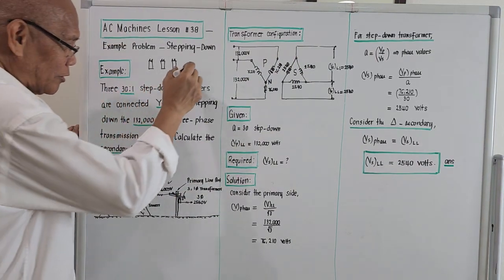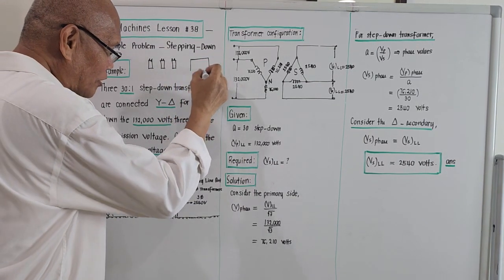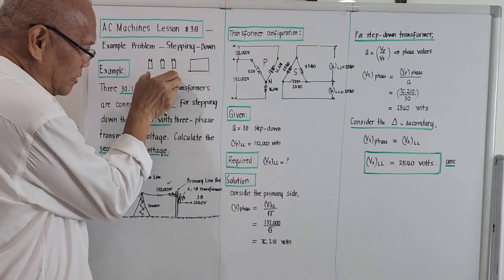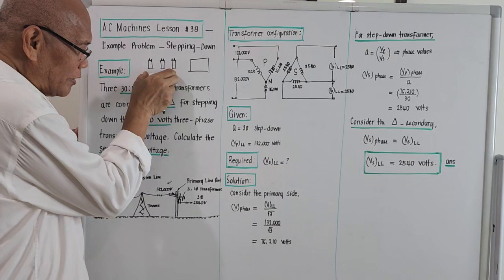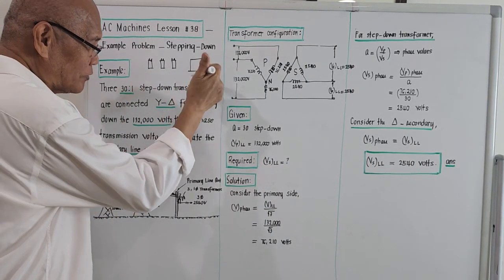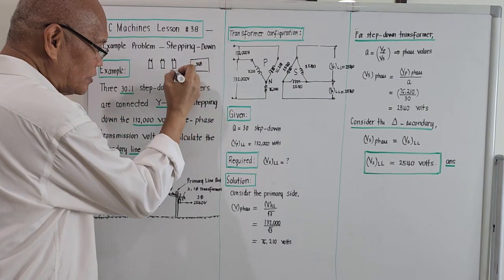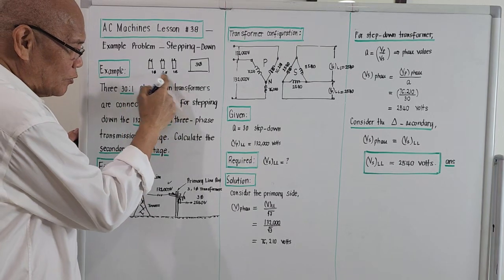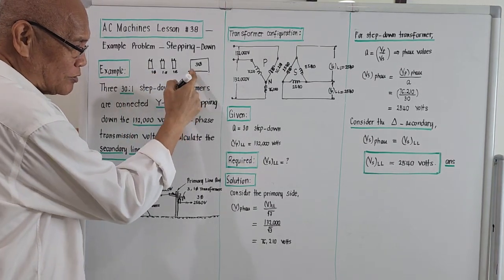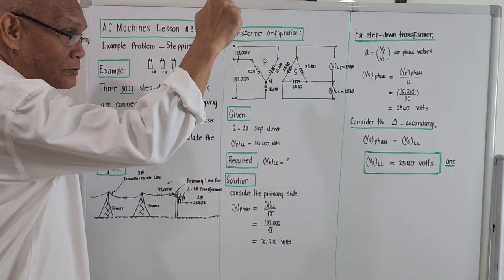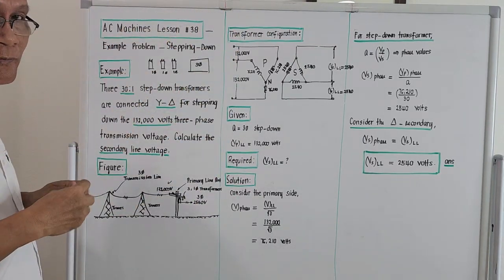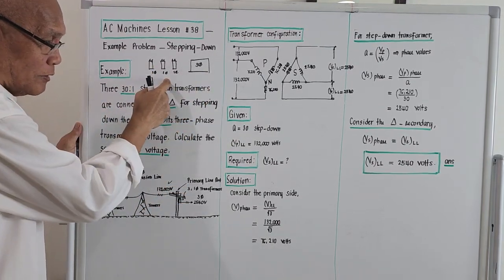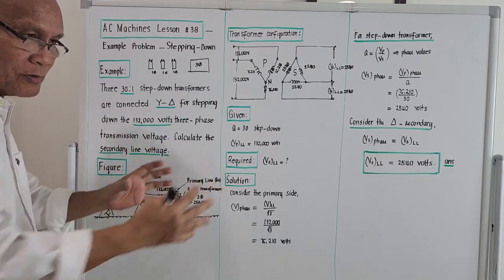So we are not talking of a single three-phase transformer, which is bigger. Actually we could create a transformer which is just one, but it will be three-phase. These are just single phase. I think this is more flexible than that one, because a three-phase transformer, if you try to put it on the post, is very heavy. If you replace this big transformer by three single phase, the weight will be more manageable.